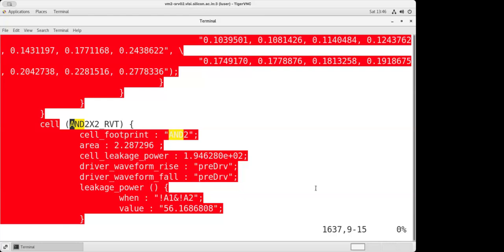When we run the scripts, I will show you that there is a certain set of libraries which you have to tell the tool, like, these are my libraries. You will not go on the internet and search for all kinds of libraries. It's not like a driver search. I'm just providing you a path, and in that you search it. So that target library syntax is there. You will provide those libraries, and then you're going to link them.